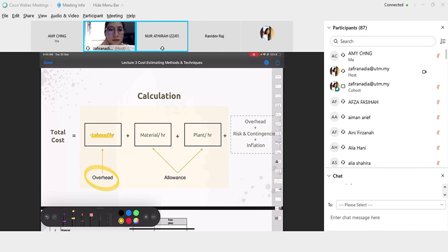It's like OT? Or is it wrong? Correct. Jerome also answered the same, OT. So consideration, sometimes you know the project, you know the client says the project must be finished in 1 year. You can already gauge, as a human, that the client will want it fast. Or they give a big project scope but still want you to deliver within 1 year. So you as a QS should know this. There's a tendency for your workers to have to work overtime. So hence the overhead is overtime cost. Put it in the labor cost. Because labor cost has 2 kinds: the normal cost and the cost for overhead or OT. So that is what you have to calculate.